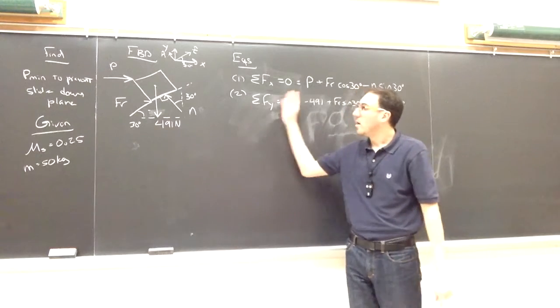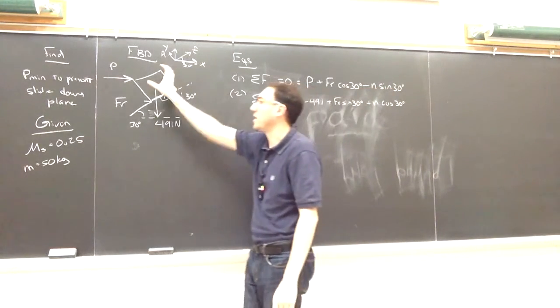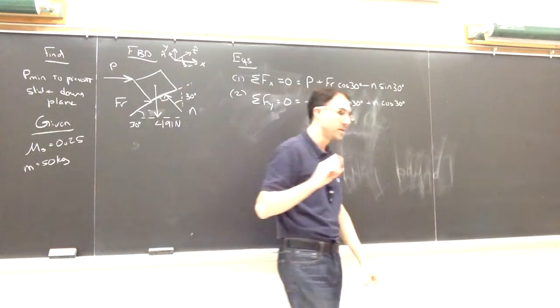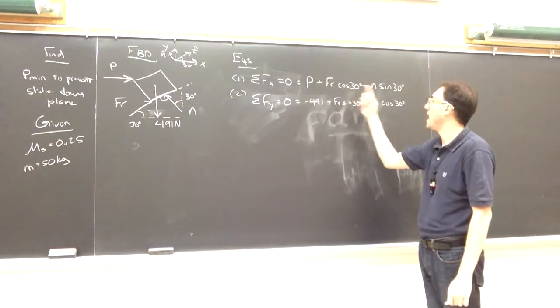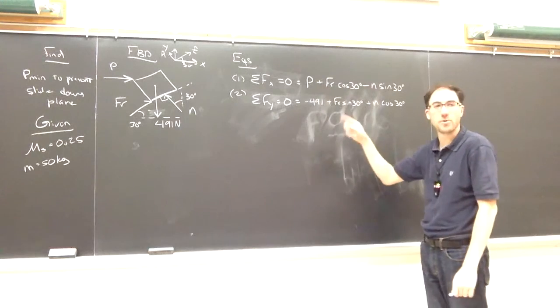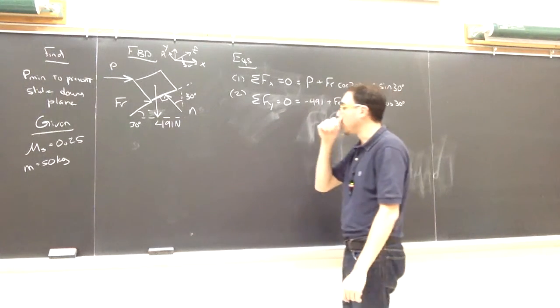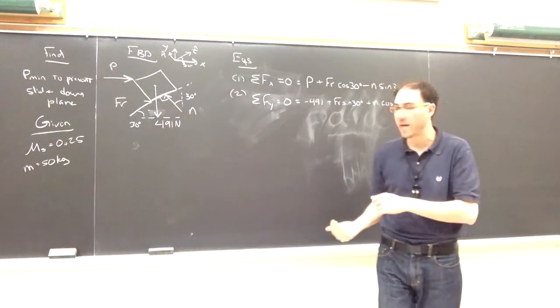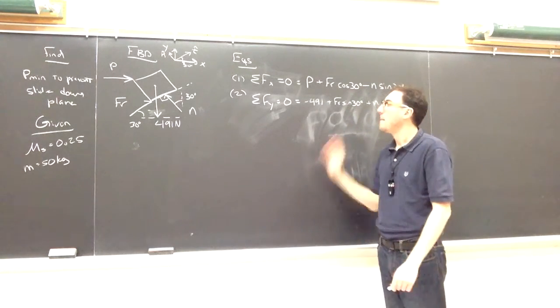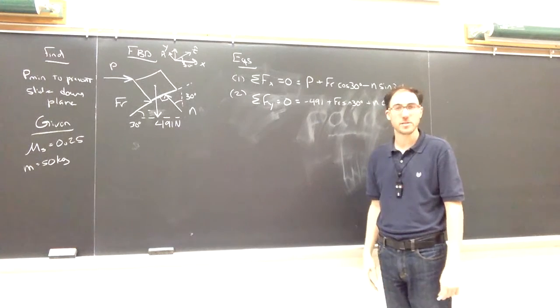As I was saying, because we don't know any of the heights or anything like that, I can't do a moment equation. So 2 forces, x and y. And if I look at the 2 equations, I still have the 3 unknowns between the two. So from the equilibrium equations, this is not yet solvable. I have 3 unknowns, but only 2 equations. But I'm done making equilibrium equations.